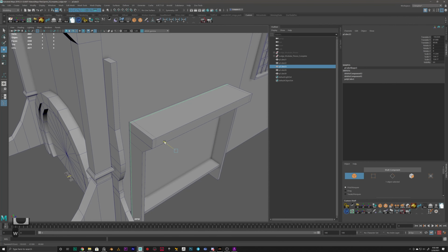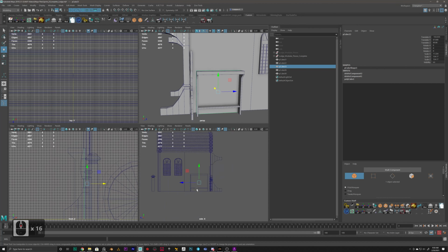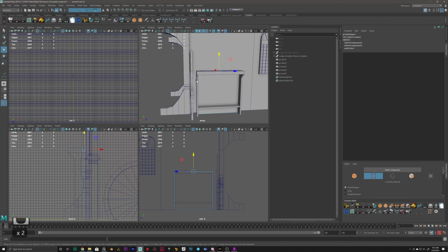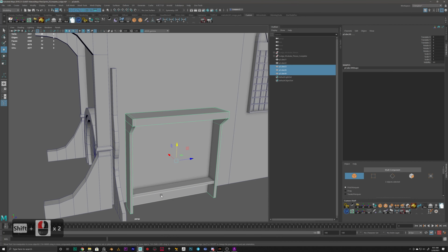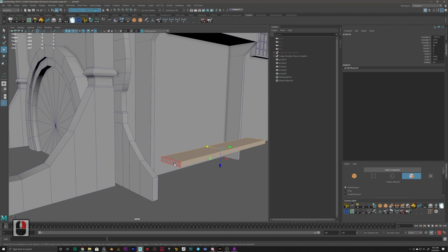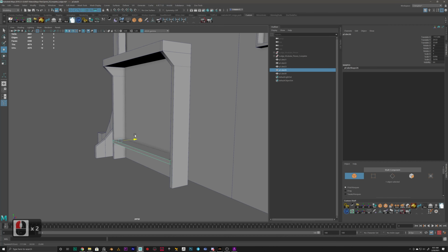Then bring this in. And you can reduce the size if you need to, because all we want is this as a back face. So I'll bring it in just like that. And select everything. Did we delete the face in the middle? We know we didn't. Oh, the faces that you don't see, just delete them. It makes it easier when you're modeling, because you have less faces to worry about.